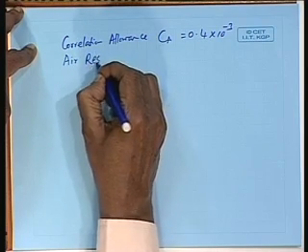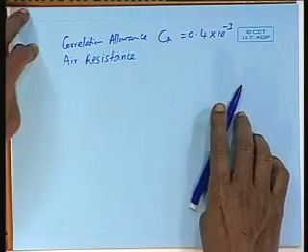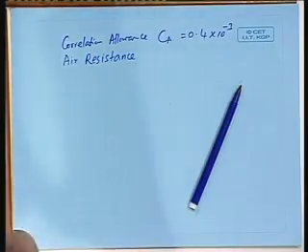Okay. Then for trial condition, for ship trial, there is another component of resistance which we must take into account, that is air resistance. When we talk of resistance to air, we will mainly consider air coming from front, and we will not consider the waves generated due to wind. Suppose it is totally calm, there is no wind and a ship is moving, will it experience any air resistance?